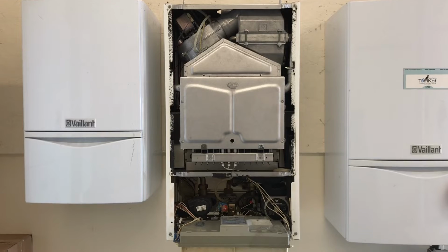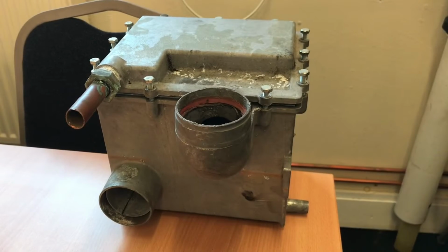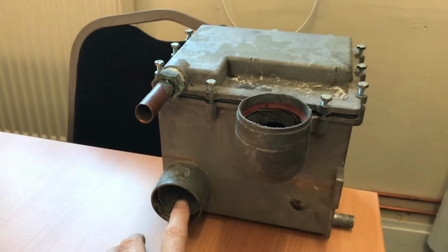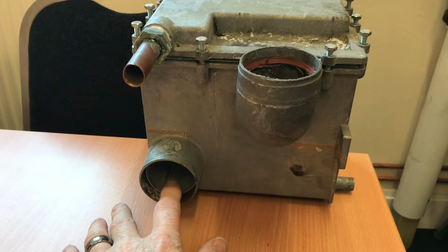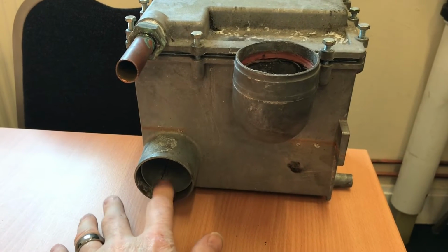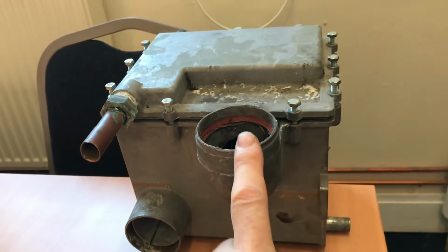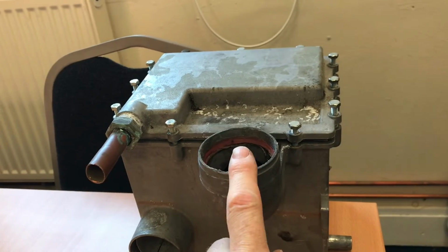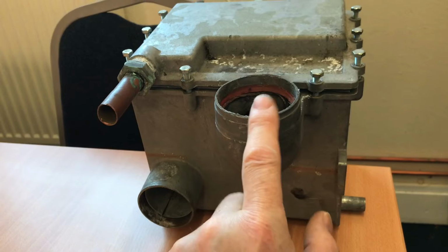Let's have a look at this secondary heat exchanger a bit more closely. This is the secondary heat exchanger I've just been talking about. What you can see here is where the fan off the top of the hood will be connected. This will be blowing the products of combustion through here. It would then exit here, out into the turret and then out through the flue. So this is how the products of combustion get in through here and out through there.